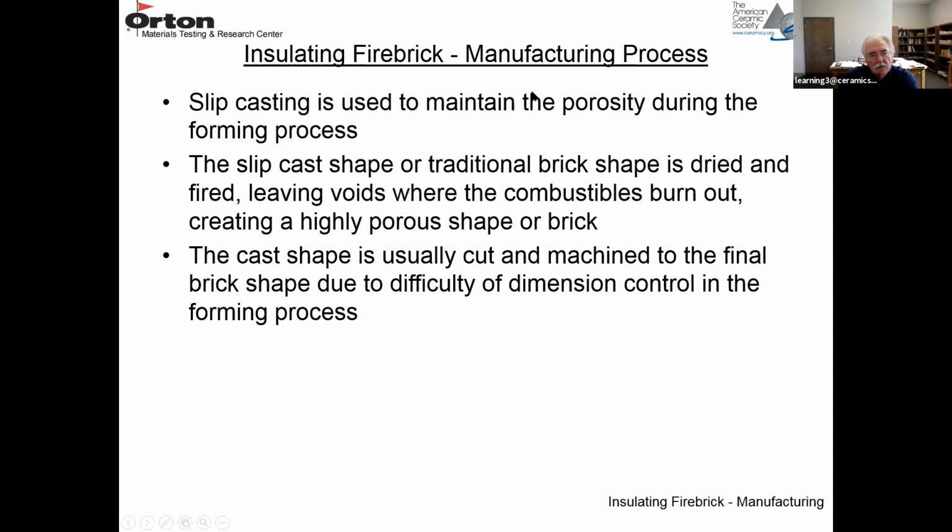So slip casting is used to maintain the high porosity level during the forming process. You don't want to apply pressure and densify it like in a pressing operation. If you cast a brick shape, it is dried, then it's fired. And when that happens, you burn out the combustibles, you leave voids where the combustibles burn out. And now you have a highly porous shape or brick shape.